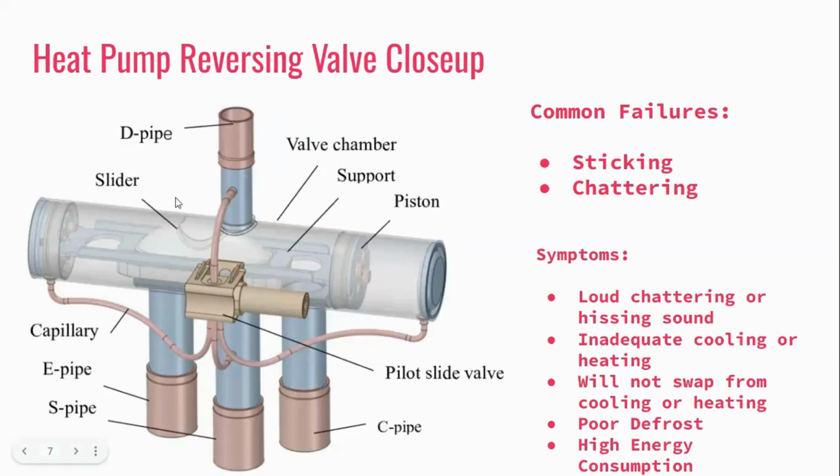So that's going to go in one pipe and out the other. So say it's going like this for cooling, and then you hit that reversing valve and it's going to go like this the other way for heating. And it does exactly what it's already doing in the refrigeration cycle as far as that goes. But instead of cold, we're going hot. Instead of hot, we're going cold.